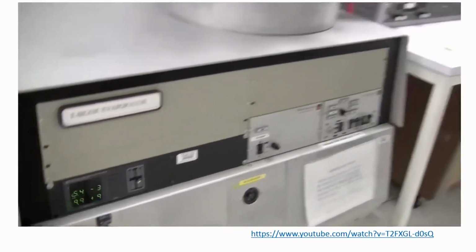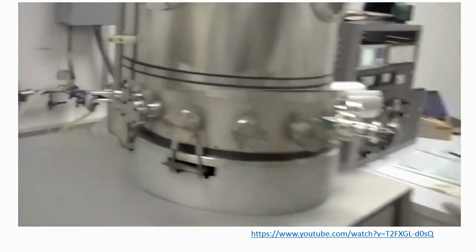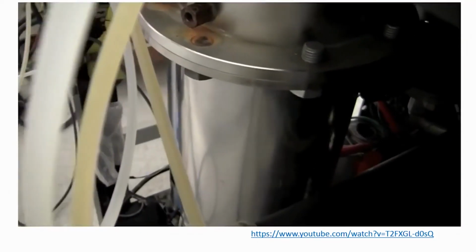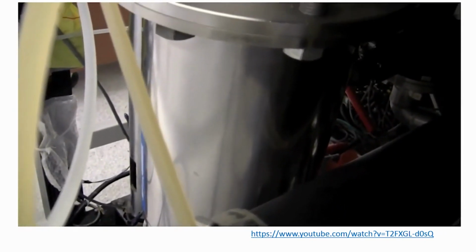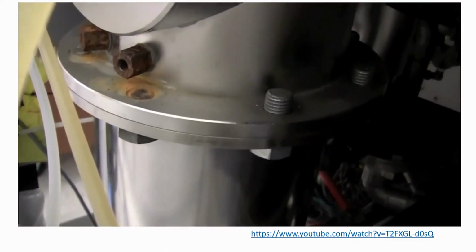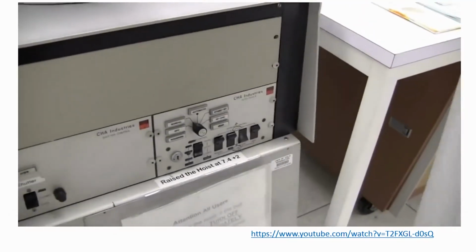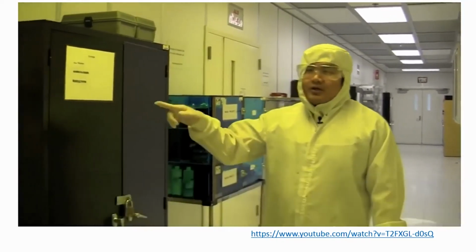If the pressure does not drop, there might be a problem with the cryo pump. It might have been dumped. To verify that, we would look at the cryo pump, which is located behind the system. And we want to make sure there's no moisture on top of the pump. If there is moisture, that means the cryo pump has been dumped, and we want to abort the process. To abort the process, we would turn the high vac off and then go to the chase and turn the compressor off. In case the cryo pump has been dumped, you want to make sure you turn the compressor off.